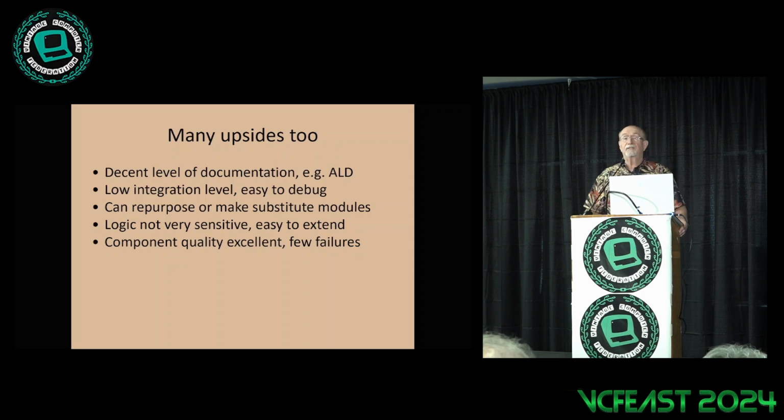And the component quality is pretty excellent. I mean, in all the years I've been working on these systems, I've never seen one of the large filter capacitors be bad. I mean, they're on spec, low ESR, at capacity. I've seen a couple of smaller ones be bad. There's tantalum capacitors on every SLT card for the power rails.